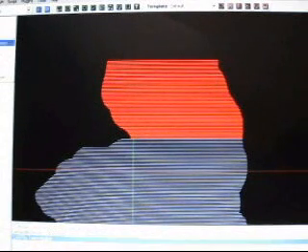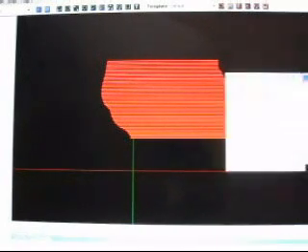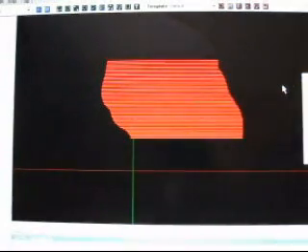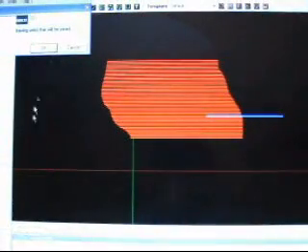Okay, so I'm going to hide the other layer. Well, actually I have that selected now, so I'll just go convert to polylines, and polylines join. Now believe me, doing it this way is going to be a whole lot quicker than if you selected this whole thing.